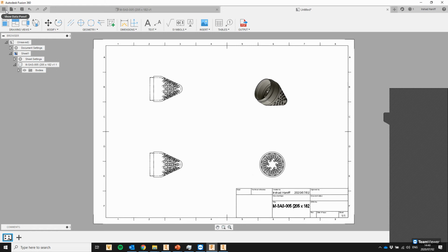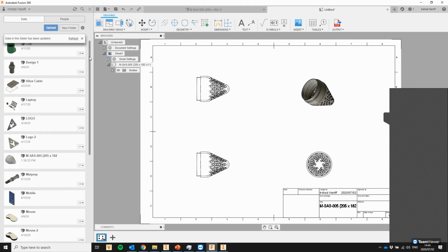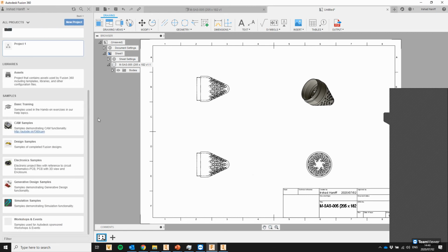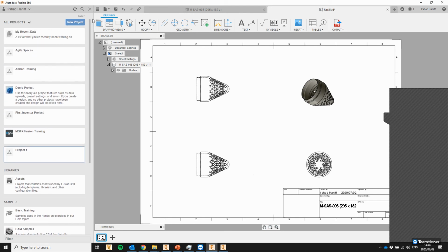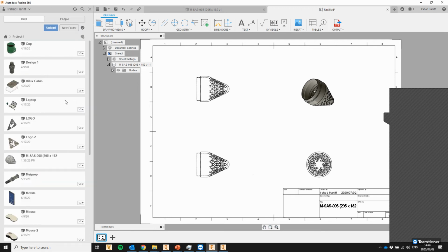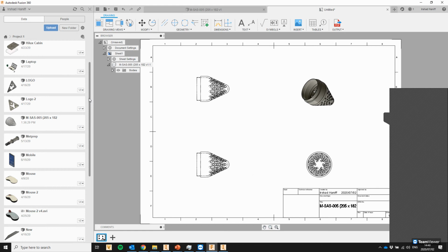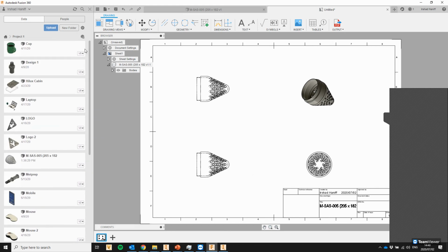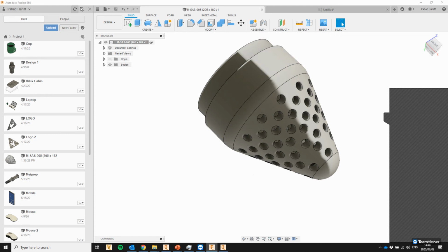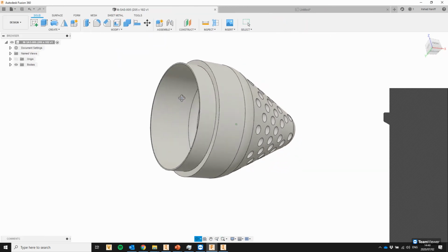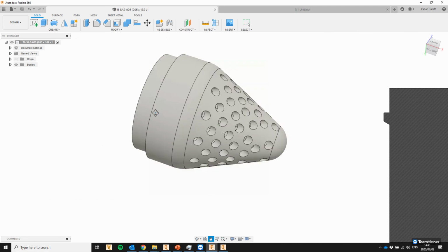The other thing we need to show that is different is the projects. So if you look at our workspace, like we said, Fusion 360 is completely cloud-based. So you'll basically work by creating projects. You open those projects and save all of your data here, and it does not make use of separate IPTs or IAMs. You'll basically draw your parts and create multiple bodies or components and constrain them the way you want to.